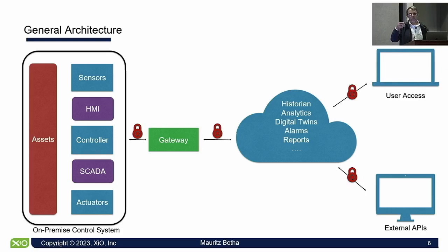With the sensors, you measure the level or the pressure or the water flow. The actuator switches the pump on and off or changes the VFD, and the controller controls that. You may also have an HMI and/or a SCADA system that will interact with those systems. And what I don't have on there, that's the new kid on the block, is IoT.